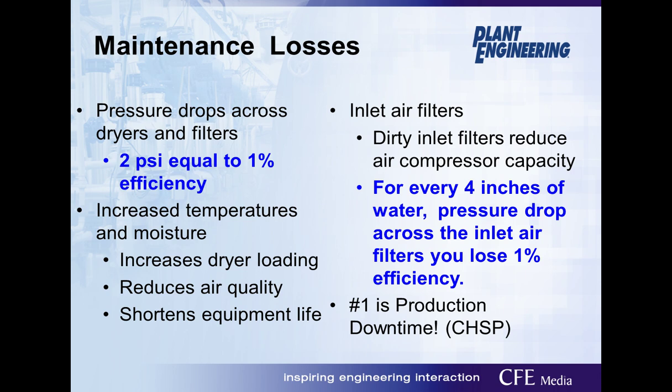And then, of course, things like inlet filters. Dirty inlet filters are going to reduce capacity. And the rule of thumb here is for every 4 inches of water drop across an inlet air filter, you lose 1% efficiency. So again, take these efficiency things and convert that necessary evil to, I need to change this because it's costing us more in operational costs than if I just went and changed the filters, okay?